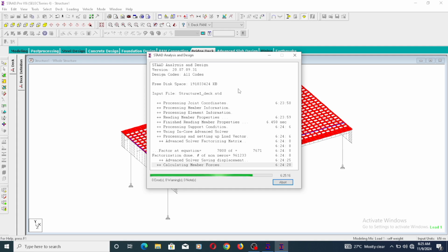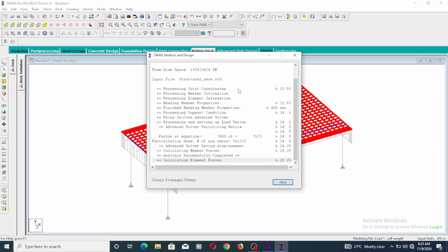All right. So once the influence surfaces are generated for the plate, we can begin to obtain various effects. Talking about the responses in terms of bending moment, shear force at various points along the beam. We can as well obtain the deflection of the beams. So the first step is to generate this influence surface. Once that is done, we can proceed to responses.